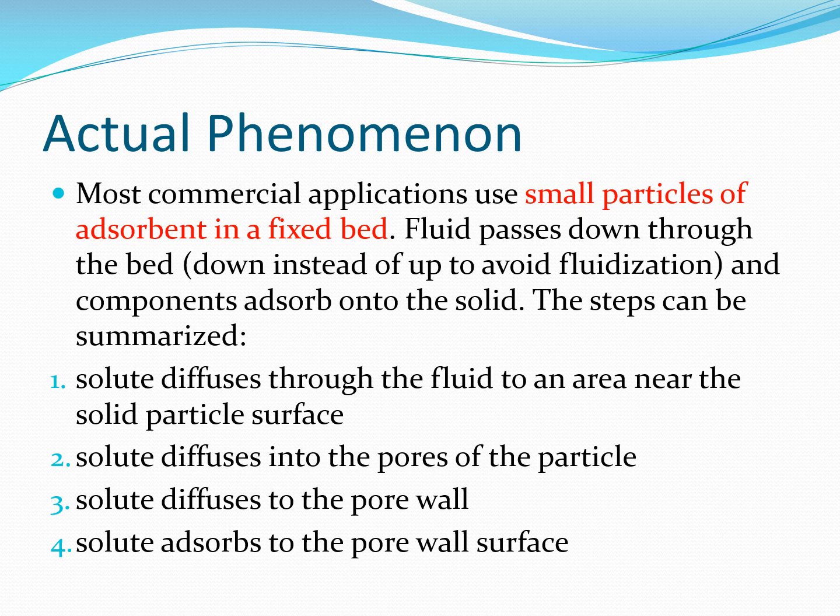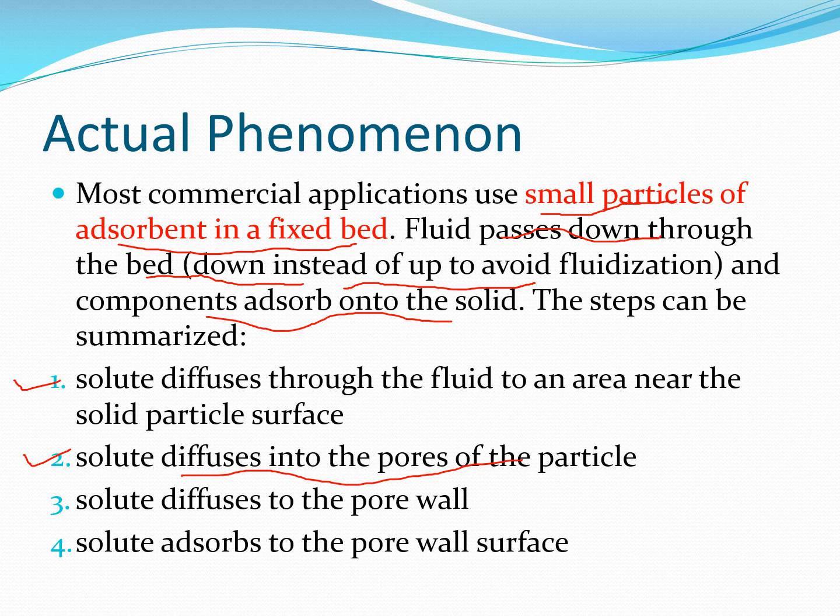So what is the actual phenomenon? Most commercial applications use small particles of the adsorbents in a fixed bed. Fluid passes down through the bed. If it's liquid, it comes from top to bottom, and if it's gas, mostly gases enter from the bottom and move upwards towards the top. Components adsorb onto the solid. So the first step is the solute diffuses through the fluid to an area near the solid particle. Then the solute diffuses into the pores of the particles. Then the solute diffuses to the pore wall, and then the solute adsorbs to the pore wall surface.